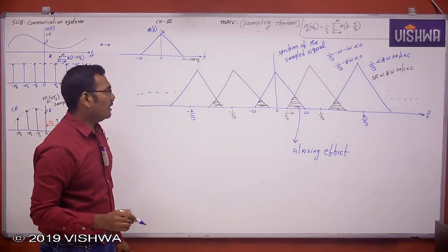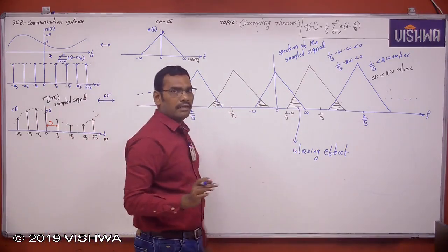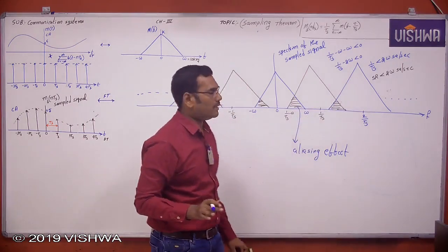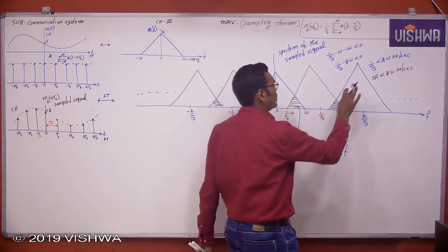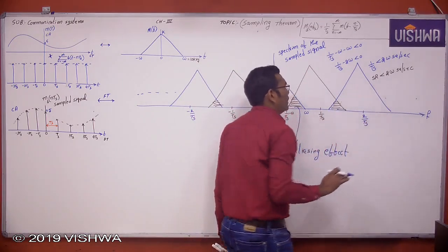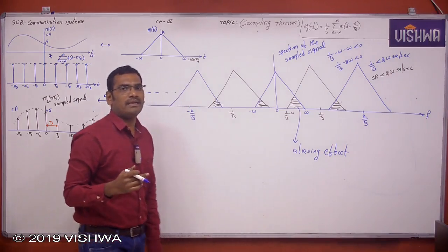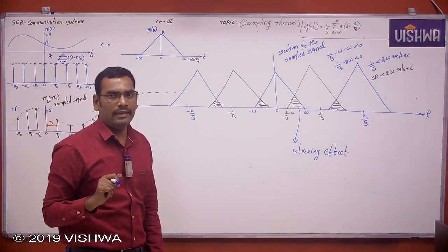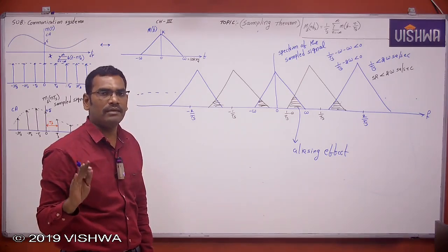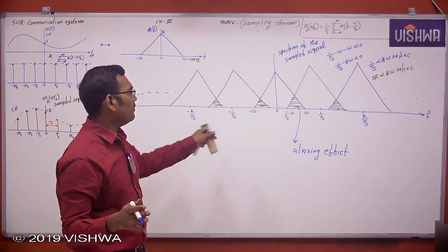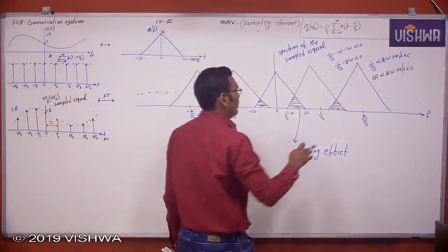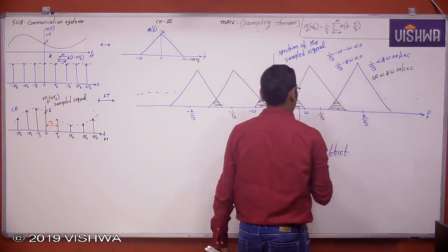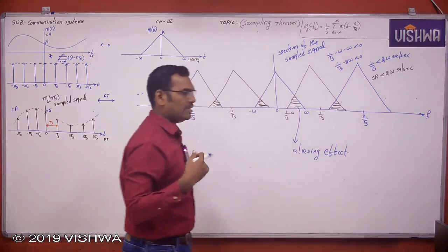Therefore never sample a signal with a rate of less than 2 omega samples per second. Always sample the signal at greater than or equal to 2 omega samples per second. Oversampling is better, and in a rare case ideal sampling, which is equal to the Nyquist rate. But never sample below 2 omega samples per second, which is undesirable, causes aliasing, and your information is definitely lost.